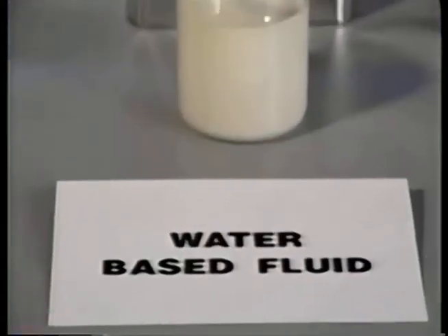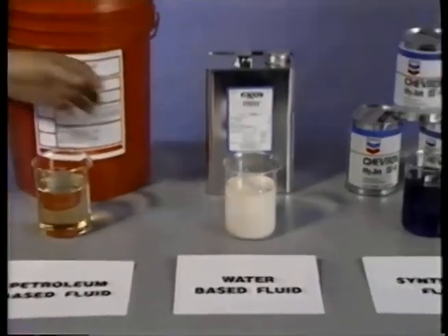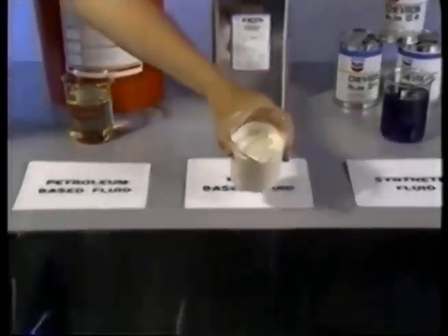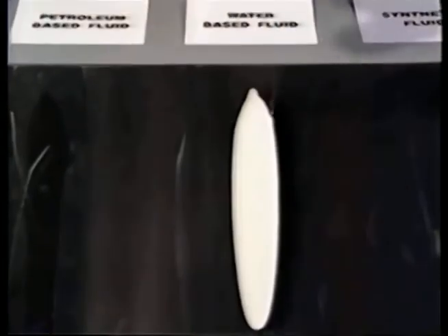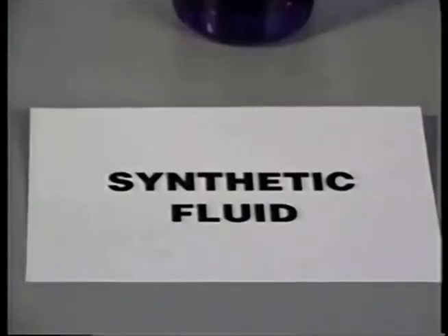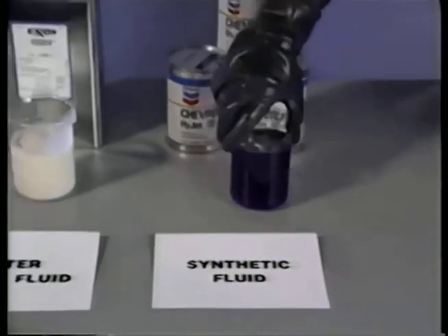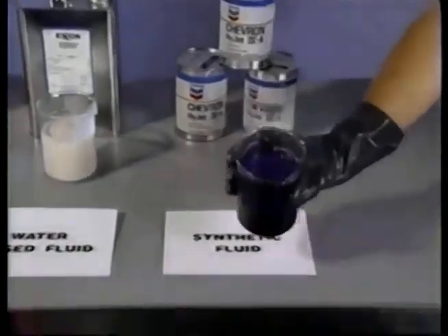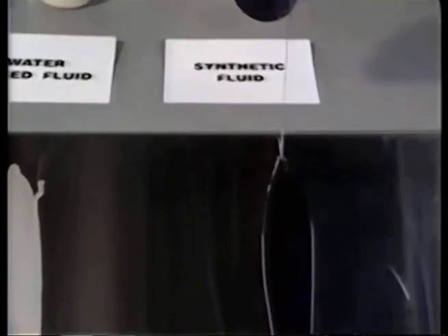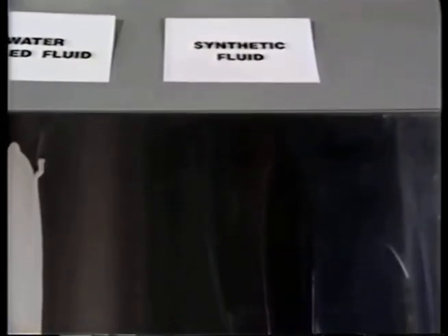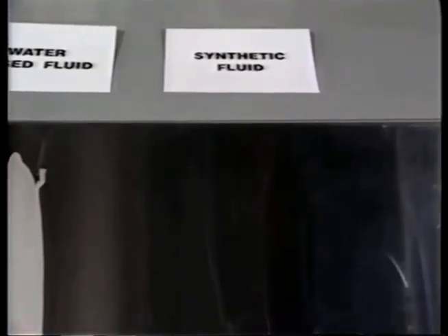Water-based fluids are often used where fire resistance is important. They are generally made from mixtures of water, oil, and other fluids. Synthetic fluids are often used as well. They have good lubricating ability and are highly fire resistant, but because they are not compatible with all systems, their use is often confined to special applications.